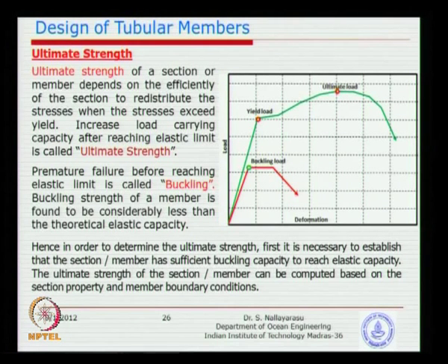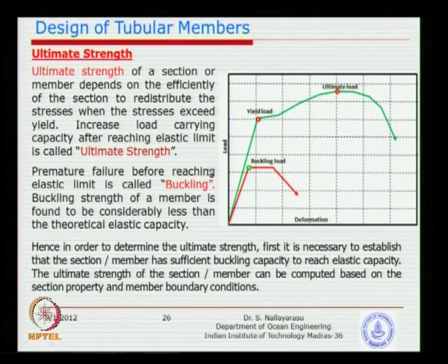For example, when you design a multi column structure, you will not be given a free hand to make the columns as big as you want, because if you have too many columns, you won't be able to use the particular property for which it was built. You have so many columns that the whole space is occupied. So there will be restrictions and you may have to follow. In such cases, some of the design will become governed by buckling, but then you have no choice.